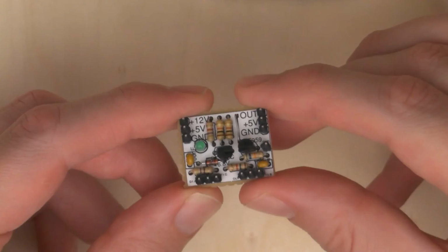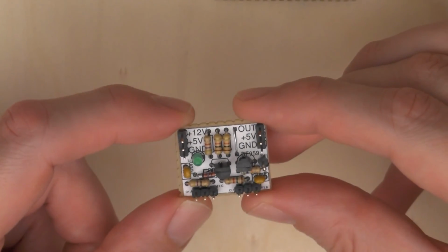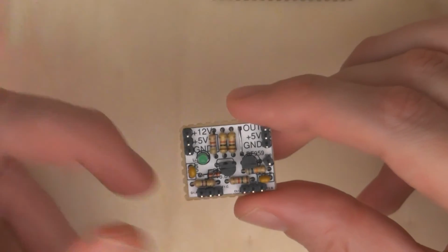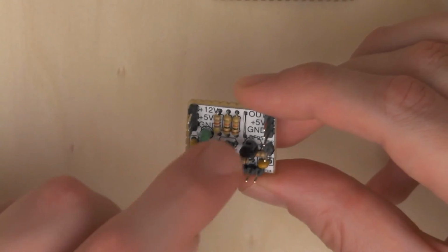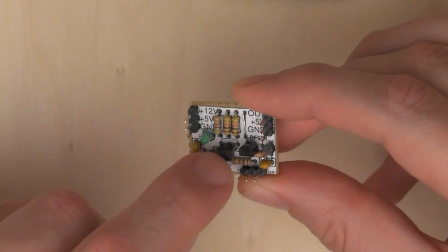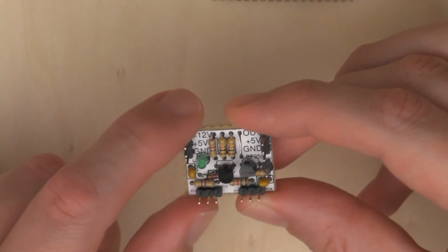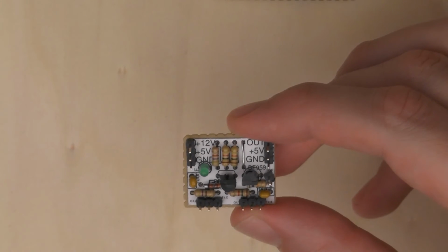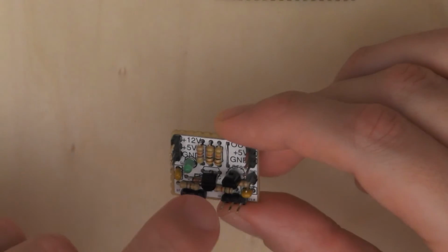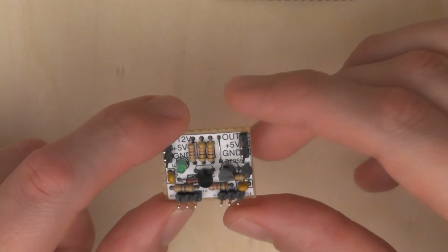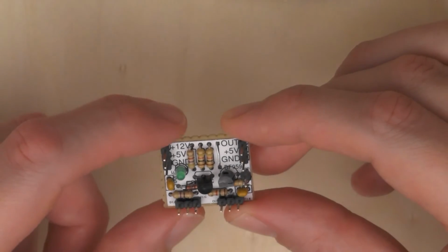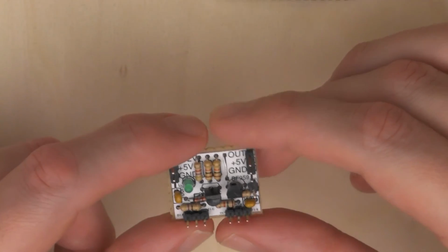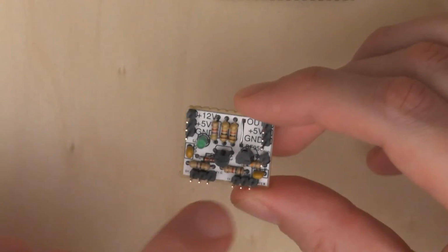This is the design I'm currently using, and it's just the core circuit of what I've got running for the test right now. 2 transistors. The first one is a BC547C because it has a higher gain, and at this point it doesn't go into saturation anyway. Then that's followed by a BF959, which might actually go into saturation sometimes, but gets out of it again much faster.